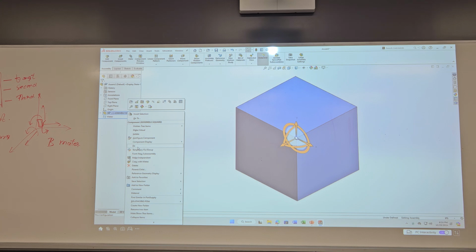And you can do it, either you bring it in and you say rotate along x-axis, rotate along y-axis, rotate along z-axis. You can use those commands, or you can drop it in, make it float, and then you can say move it with triad, or use the shortcuts with the control, the buttons with the mouse, and move it into the orientation which you need.